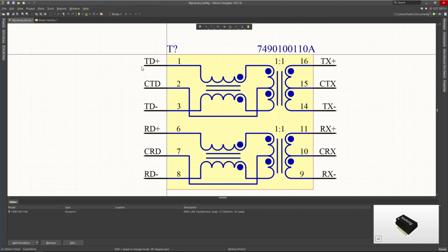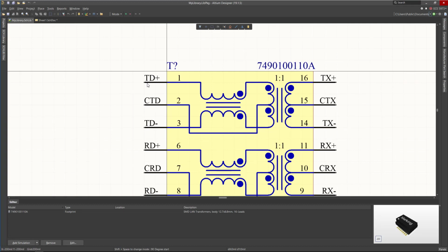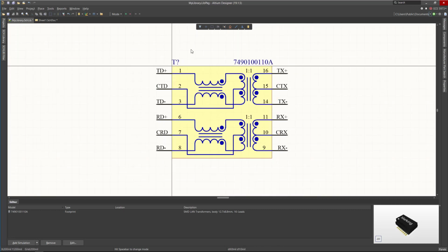But now we will have a problem if you try to move this component. Look, you cannot select this component because, you see, I can only switch two blocks. Each one is 100 because the visible grid is 100. I can only snap into 200. So we can do it back. If I click on G, it's 10, and this is 100 now. Okay. Now let's go back to the slides.